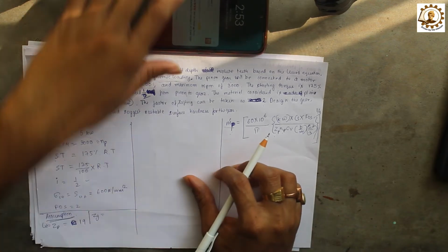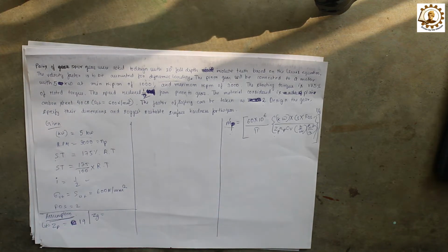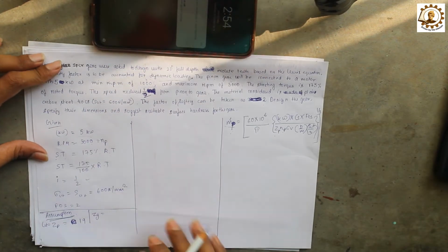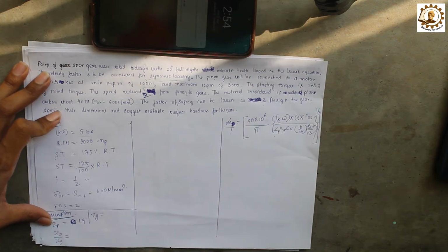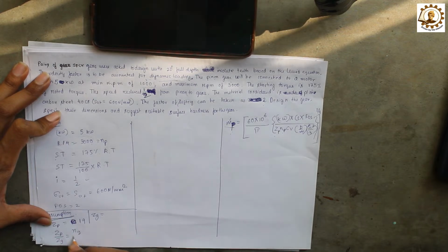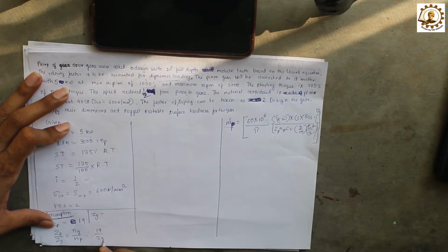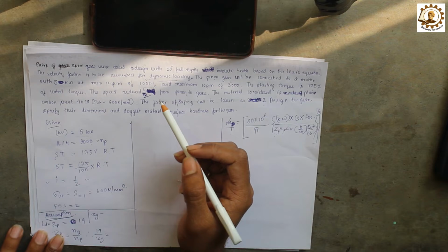How can I calculate it? The simplest way is to use an old methodology we studied in our previous classes. We know that Z_P by Z_G is equal to N_G by N_P. Okay. Now, therefore, I know Z_P is 19. I don't know Z_G. Before providing the value, we have been provided with this value over here, i.